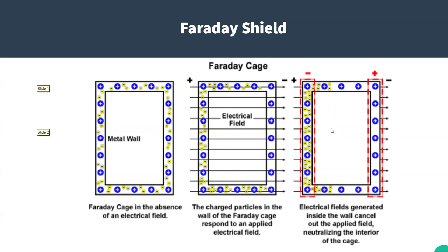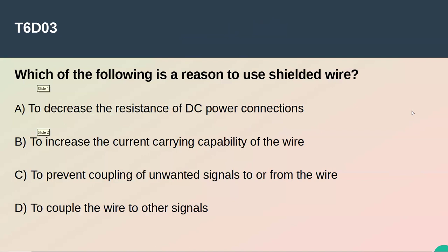But the principle of a Faraday cage is that it may have holes in it or penetrations, as long as they are smaller than the wavelength of the wave you're trying to block, it won't go inside the cage. Your car acts as a Faraday cage, which is why your handy-talkie won't work well inside of a metal chassis car. You kind of have to hold it close to the window or have an external antenna.